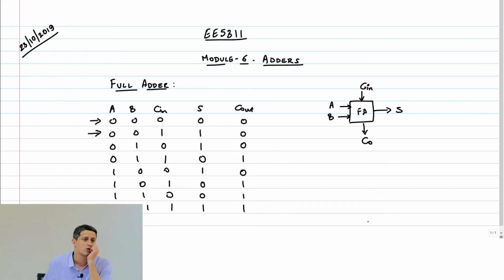What happens to the carry out in that case? 0, 0, right? It means that irrespective of the input carry, the output is just killing the carry, right? The carry is just gone because the inputs are basically 0, 0. So this is what we are going to call kill, K.